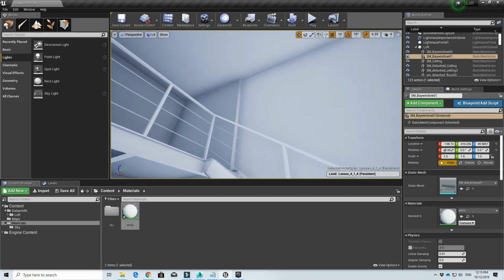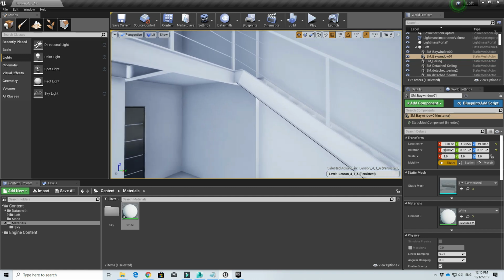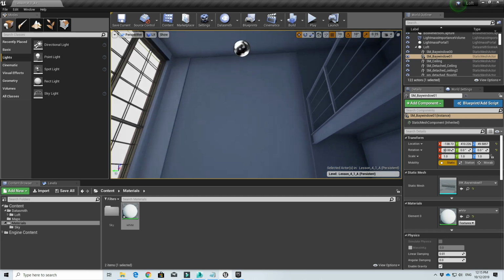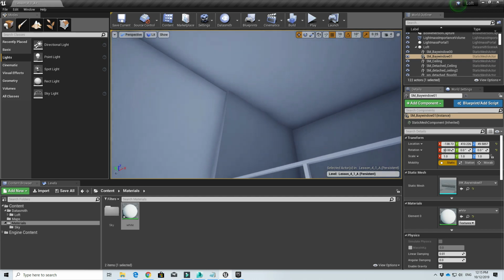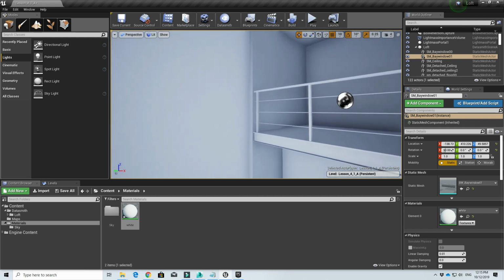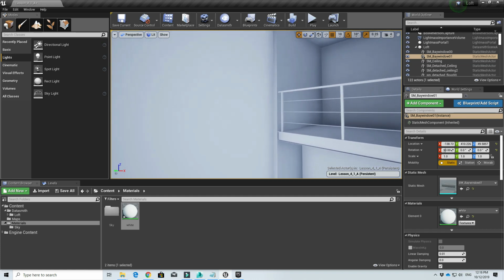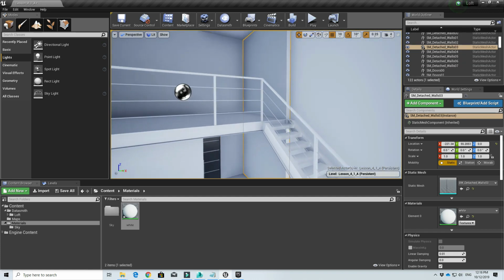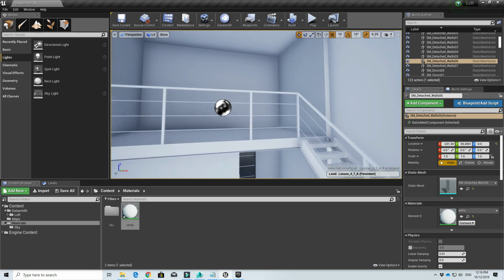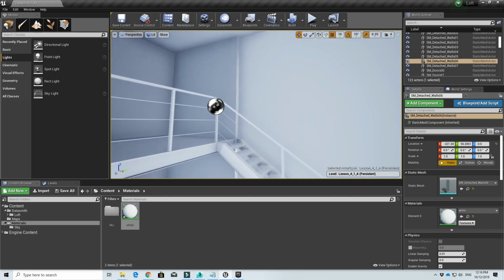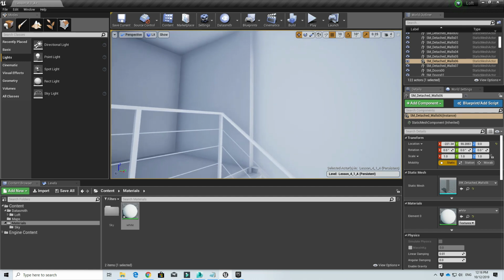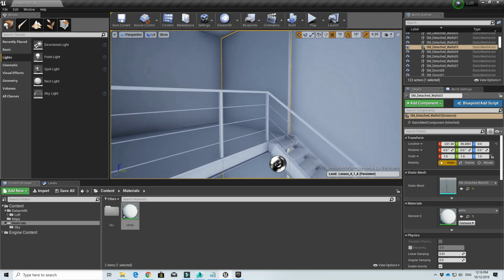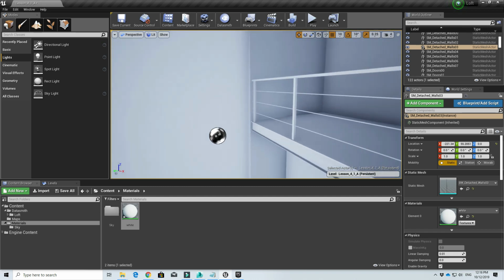Okay, so we have done a preview build and the room should look like this. Just a few things to take note. If you have done the modeling rightly, your walls should be quite clean and nice and white. This is not photorealistic yet, but there are no very obvious blotches and stuff like that, because this is using the optimal light map resolution.